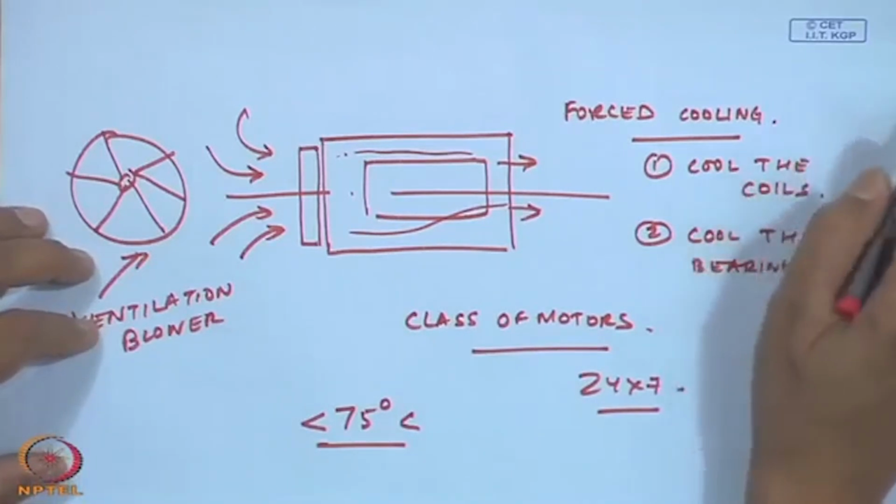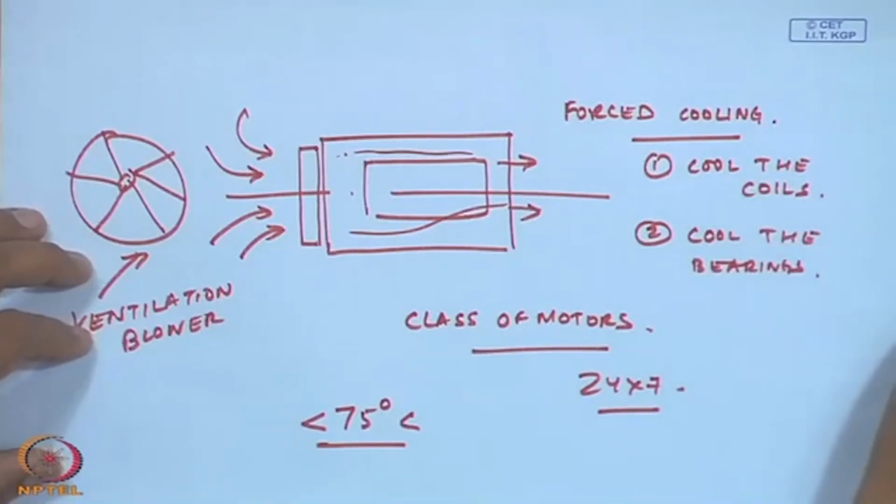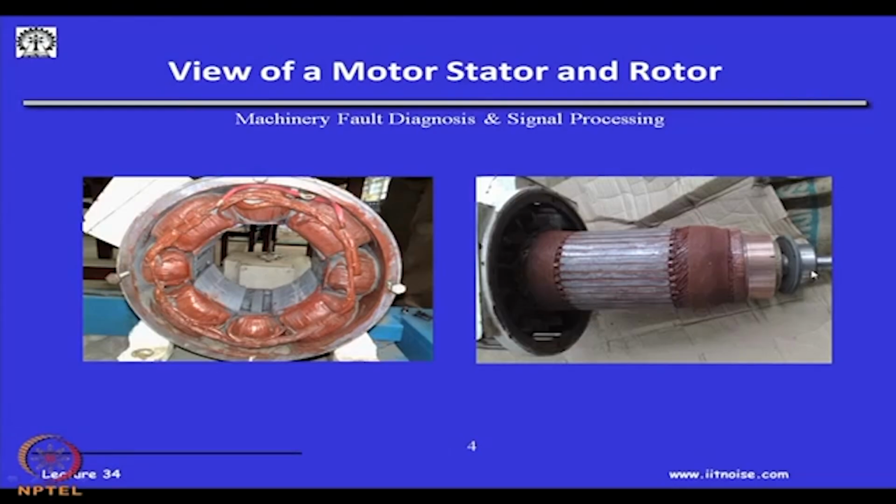Okay. And in fact, in some special motors, there are alarms which let you know that if the bearing temperature is increasing, either the motor shuts down, or we have to have an extra cooling unit to cool the motors. So, this could be a serious problem, because once the motor heats up, there may be unequal differential expansion. One conductor may, for some reason, expand more than the other, and this differential expansion will lead to misalignment, will lead to having no concentricity between the rotor and the stator. One will deform more than the other.